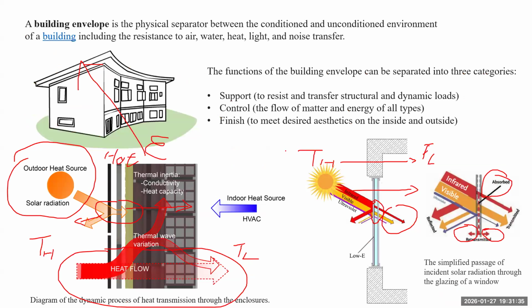Now we can clearly see, however, that for this we also didn't consider the emissivity of the glass. Although we considered the emissivity transmitted into the indoor air and the outdoor atmosphere, we didn't consider the thermal emissivity of the glass itself, especially in the atmospheric window. Unluckily, glass also has a small thermal emissivity.